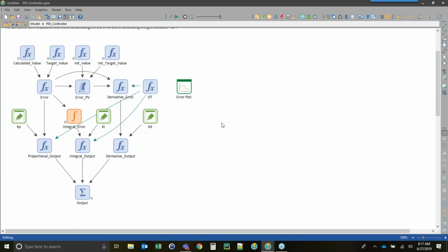And you can look at the calculations themselves. Essentially, they're all based on some sort of error that we come up with. The error is a function of the target compared to the current measured value that we're reading, in our case, the tank level. Now keep in mind that all of this can be done for other types of systems. It doesn't have to be a tank of water. It could be, like I was showing you earlier, the temperature in the room, or any kind of system that you might be modeling in which you have to control a signal that changes that system.